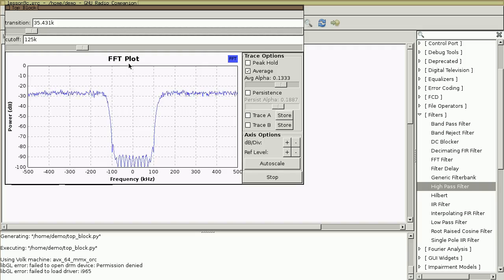If you imagine that this frequency domain is cylindrical, remember that it's periodic. So if you go off one edge of the plot, you come around the other edge. So in that cylinder, depending on how you look at it, this might look like a band pass filter or a band stop filter where we're stopping this band right here.